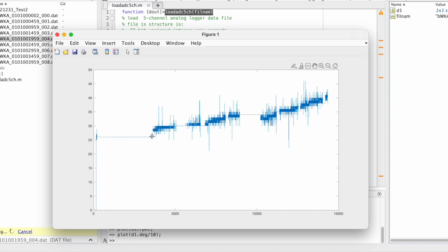And then because the controller needs to convert this AC current to charge the battery, of course there will be some losses, and this will dissipate as heat. And you can see here how the temperature slowly rises. Again, this is 5 minutes. I believe it will flatten out somewhere, but yeah, so this is still fine. We have a temperature of maximally around 45-46 degrees here.